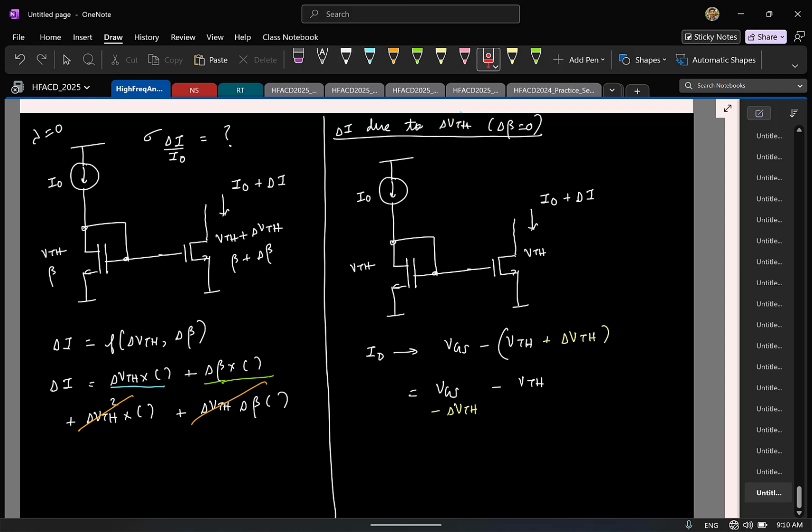So which means now I assume that the two transistors are matched. The delta VTH mismatch I'll have to add by making sure that the gate voltage for this transistor is different from this gate voltage by delta VTH. And how do I model that now? You put a voltage source in between the gates so that the gate voltage is dropped appropriately. So this should be the polarity. Again, the actual polarity doesn't matter because finally you are only interested in standard deviation and variance, so those don't matter. But once you assume some sign, stick to it throughout your calculation.